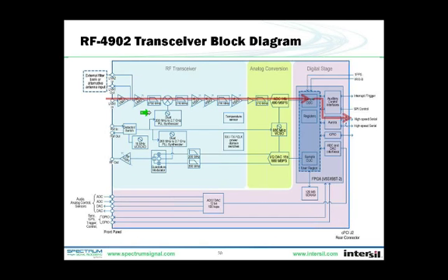The second down conversion stage, including most of the filtering, is done digitally in the FPGA. This allows the user to select the IF frequency and bandwidth to suit the signal environment. It also has a high-speed serial interface from the FPGA to a digital baseband processor card, which is not shown here. The transmit path uses a 0 IF configuration with the dual DAC transmitting both I and Q.